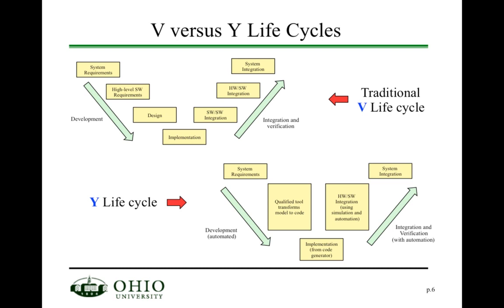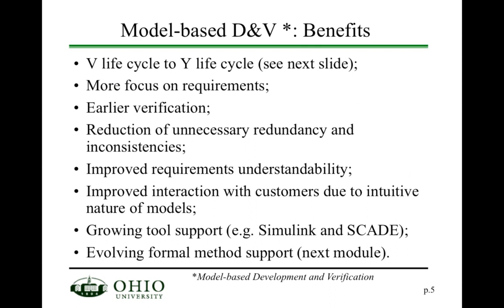In a lot of cases, you can even select that this source code adheres to software standards like MISRA-C. So there is more focus on requirements, especially when you talk about the design models, because you start looking at the details of what you're going to be implementing. And the nice part is that you can simulate, so you can already do some early verification of these requirements in simulation.